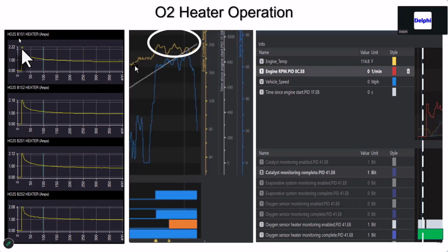Some of them you start up, let idle. Some you start up and you've got to get into a certain fuel trim cell and it will run. This one here was off of a Toyota. And if you notice, we're up here at cruise right now. This is a high-speed cruise. And this orange one down here is the O2 heater. So the CAT is run, the O2 is run, and the VVT is run, and the O2 heater is actually running last. So the other thing I want you to get out of your mind is this thing, there's an order to this. This is where patterns can be deceiving. This was the cold engine, the heater ran at cruise.